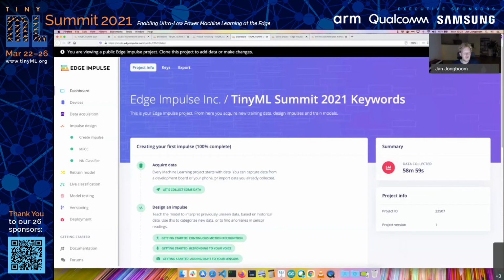But in general, I think that ML projects can be much more efficient because you don't need to send anything to the cloud anymore, but it still costs power, right? So duty cycling is still really important. If I only need a conclusion every minute, don't constantly be sampling, just sample once a minute and get some data and do the conclusion then. The same way as you would deal with network activity, for example. Yeah, this is very application specific as well.